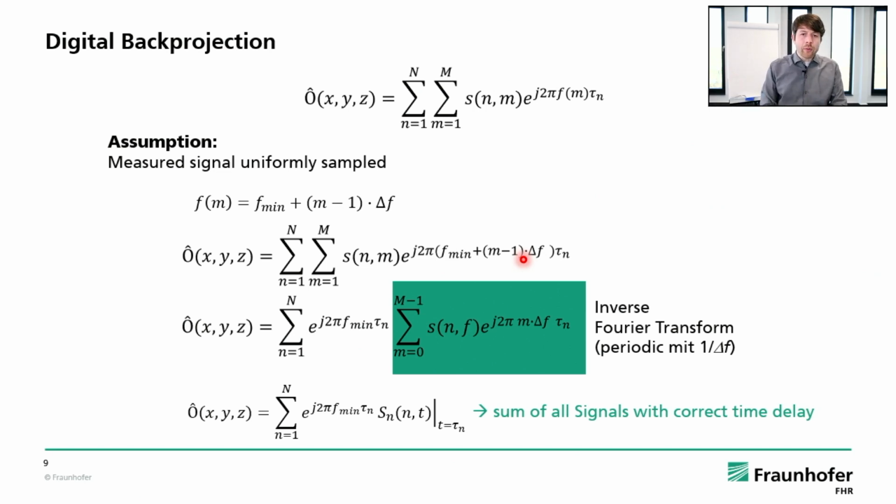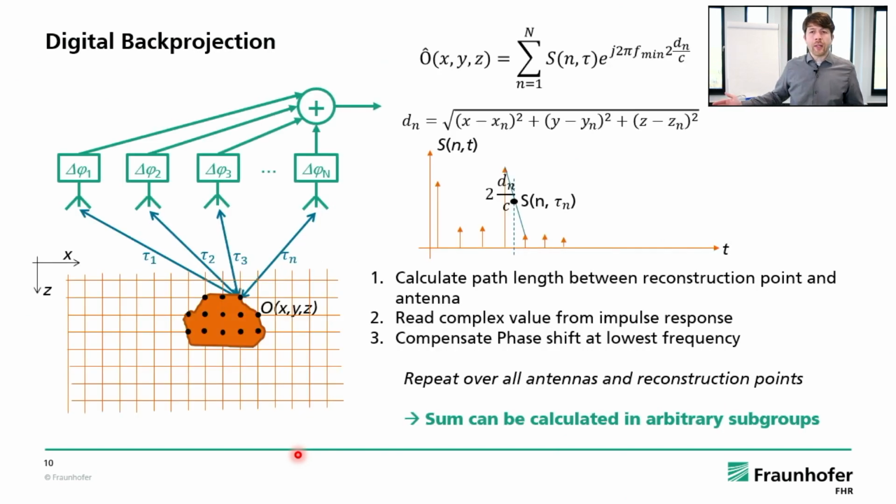So basically, after applying the Fourier transform, you will see a certain delay in a certain bin. Depending on the time delay, or the distance, you will see objects or reflections in different bins, but they might reappear depending on your spacing, because you don't have an infinitely dense spacing. But of course, if you use this, you reduce the entire sum by one dimension, which is far more efficient. Mathematically, it's exactly the same, just as we've done before, only for equidistant spacing.